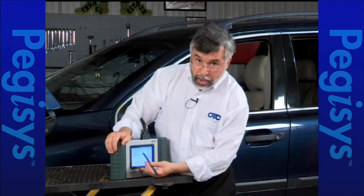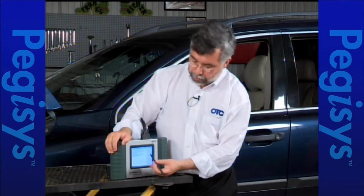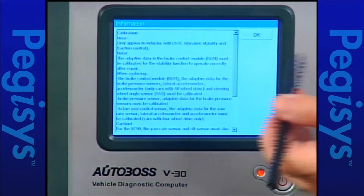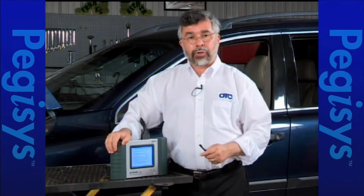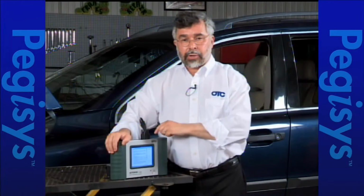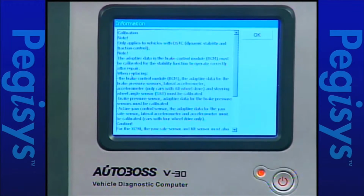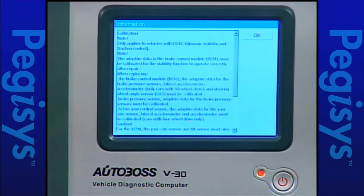It will now come up with our diagnostic test menu. Then I'll tap on calibration. When I tap on calibration, up comes a warning screen or instruction screen. The instruction screen is saying that you are going to do the testing if the vehicle is equipped with a DSTC or Dynamic Stability and Traction Control module. It's also giving you a warning that you need to have the vehicle on a flat surface.